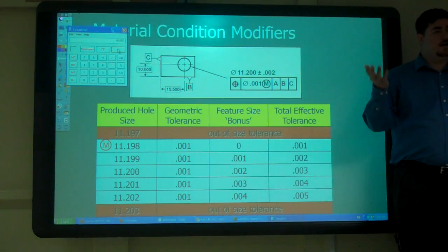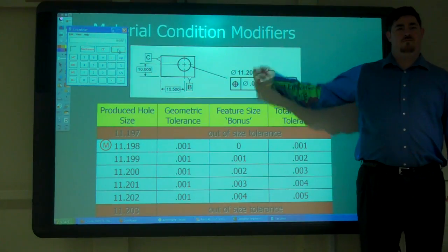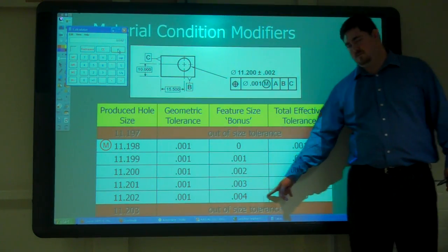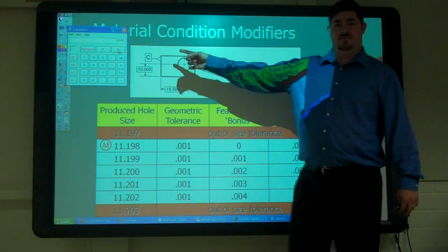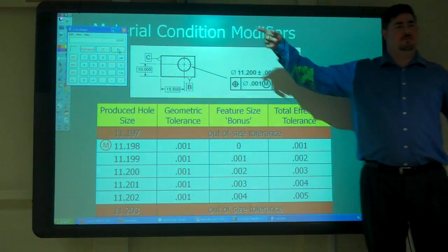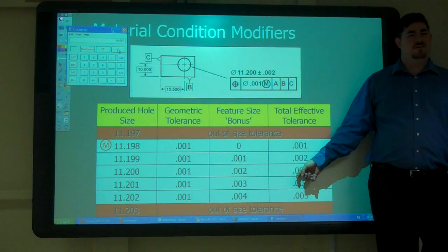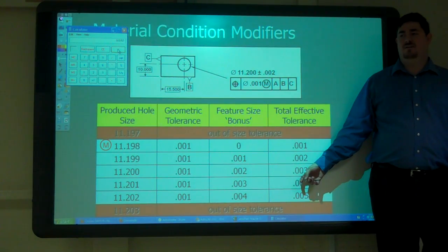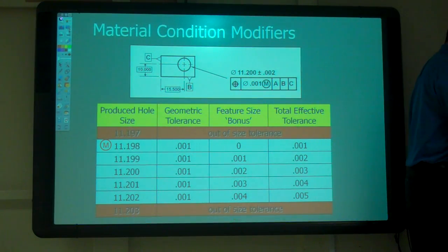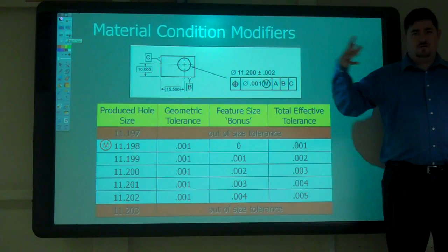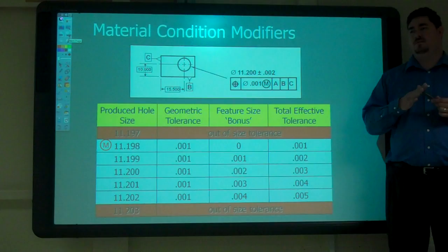That's 15/1000 of a square inch. So 5 times larger tolerance zone because of this now, at least material condition. So now we've got, so that's 500%. So now we're at 557% more tolerance space. Right? That's kind of big. Yeah. So better.